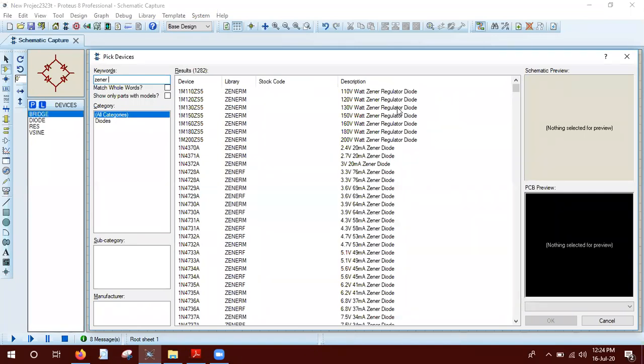We told you that the Zener diode is that particular diode that limits the voltage in the output section. Suppose I want to fix the output at 10 volts. At that time, you will use the 10 volt Zener diode. Next, suppose I need to fix the output at 8 volt or 5.5 volt or 5.1 volt. So you will use that.